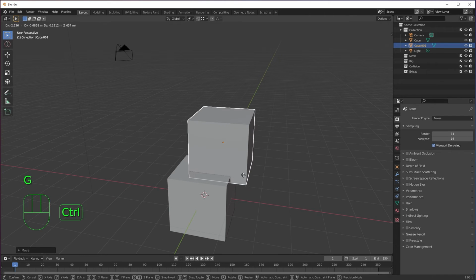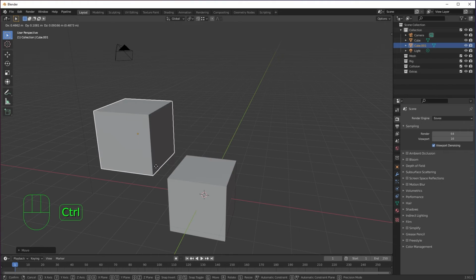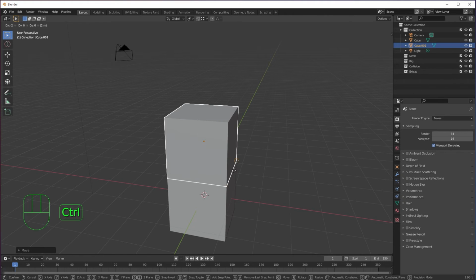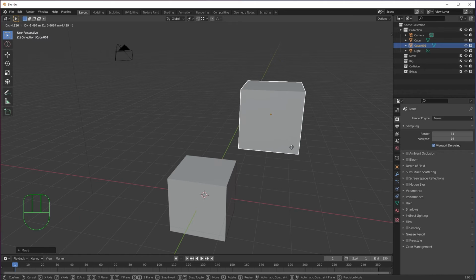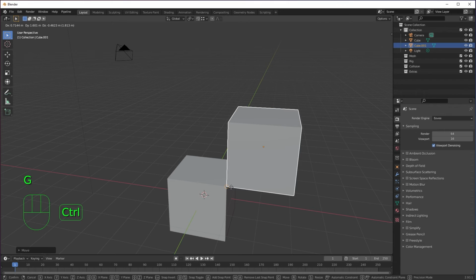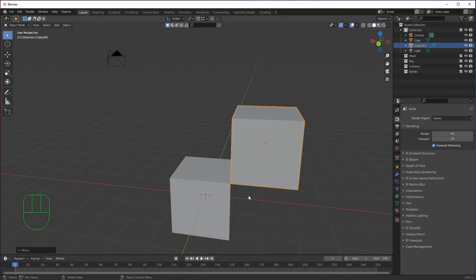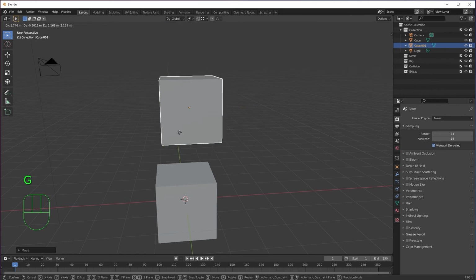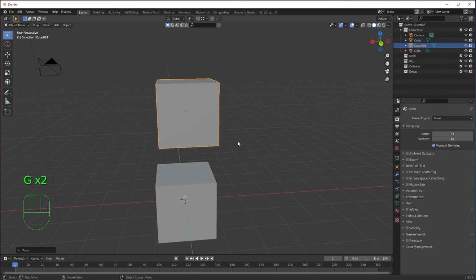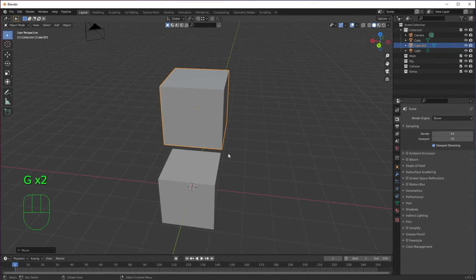The same thing applies here as well. As you can see, if I snap it this way, it wouldn't snap with the offset. But if I move my box here, and then press G and hover my mouse again here, their nearest edges will snap to each other. So that is another snapping technique which you'll be using a lot during your home modeling tutorial.